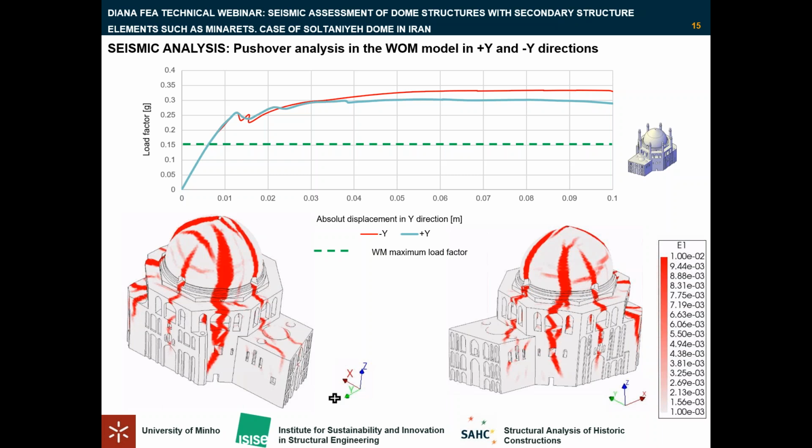This discrepancy could be attributed to the observed structural asymmetry and a slight reduction in the thickness of the surrounding walls, particularly noticeable in the third floor, which we saw the effect of this asymmetry also in the second scenario and the result of the model with minarets.